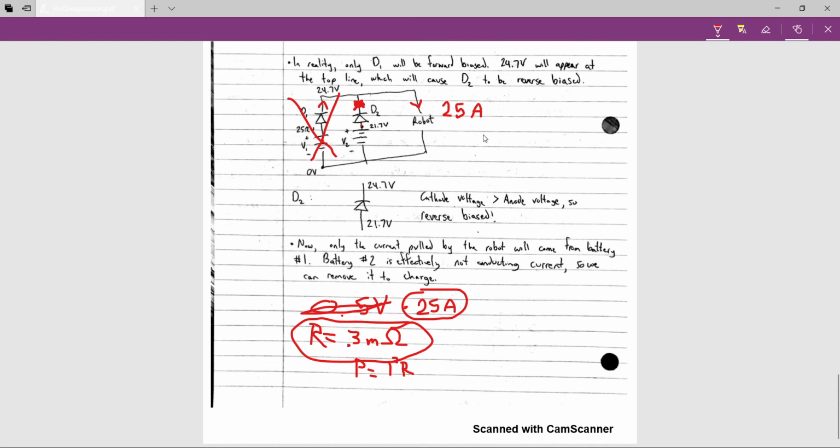If it's a 24 volt item, maybe it can go from 22 volts all the way up to 28 or something, and it can function properly. So maybe 21.7 was just barely cutting it. But if I drop another 0.5 across this diode, 21.2, maybe it's going to have some issues since that's less than this threshold. So yeah, just some stuff to think about.